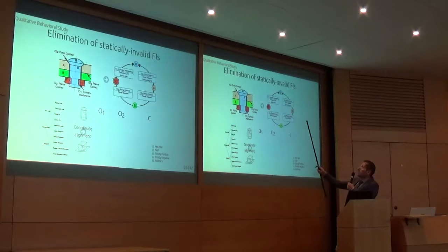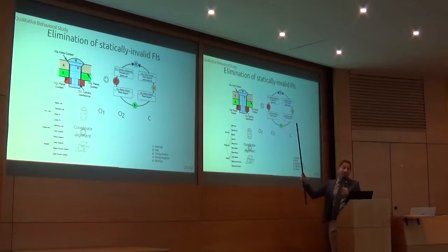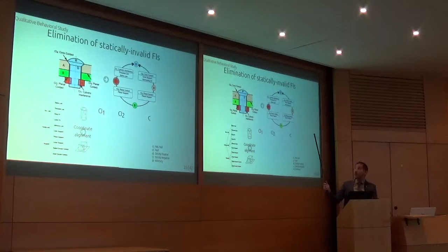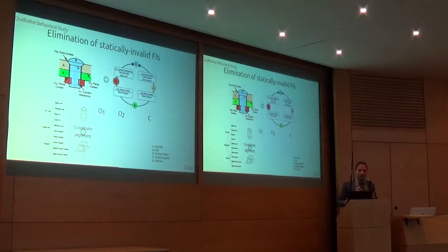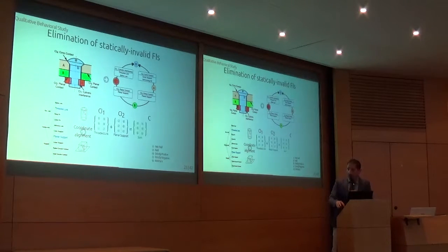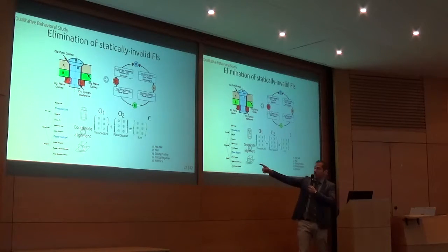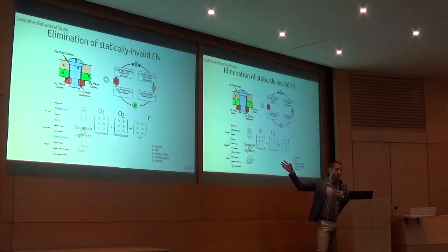In this case, this component has two interfaces, one that can only be interpreted as planar support, the other that can be interpreted either as a threaded link or as a spline link. This makes the total number of solutions sum up to 2. We browse each solution, and each time, say for the threaded link and planar support solution, we borrow wrench screws from the functional interface taxonomy and we sum those wrench screws.